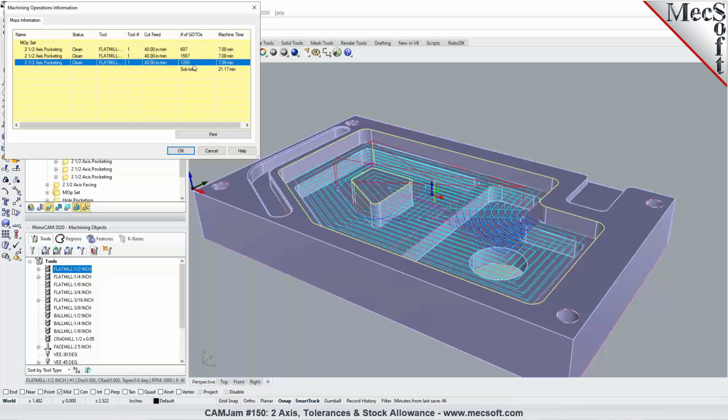And the last one you're seeing is the arcs being fit to the toolpath. So with the tighter tolerance and arc fitting, the number of motions is about 2 times. Fitting arcs to toolpaths also makes it smoother and easier on the machine to work with. So the tighter the tolerance, the more go-to motions and more lines of code in your posted G-code or output file. I hope that answered your question, sir.